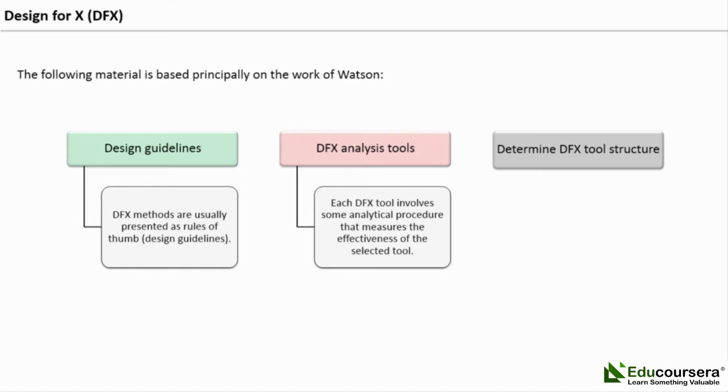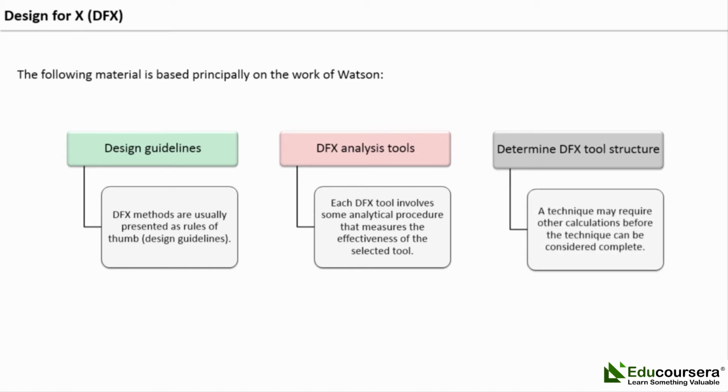Determine DFX tool structure. A technique may require other calculations before the technique can be considered complete. An independent tool will not depend on the output of another tool. The handling analysis, insertion analysis, and number of parts are all capable of being calculated, but the total assembly time requires subsystem times for each component.